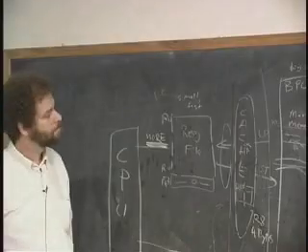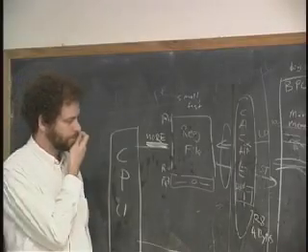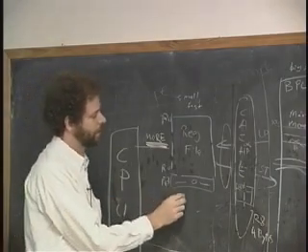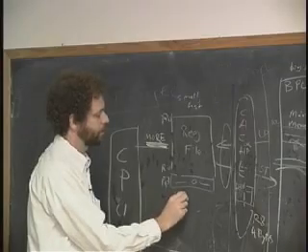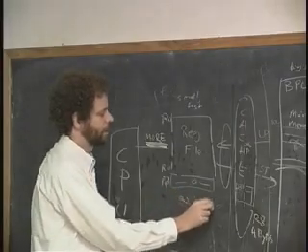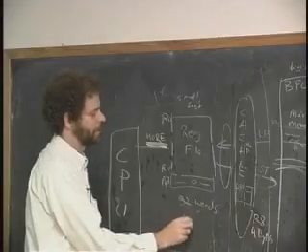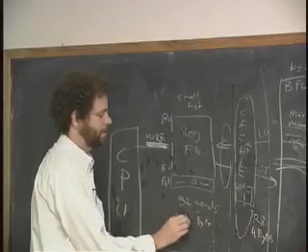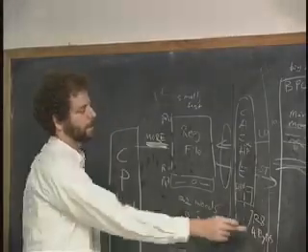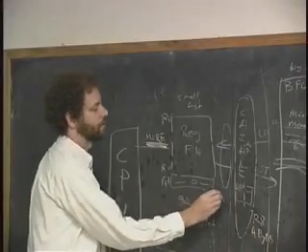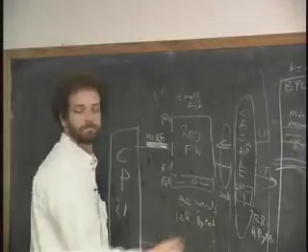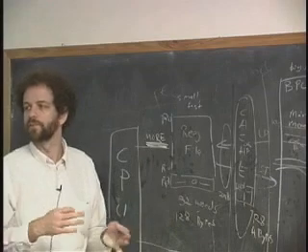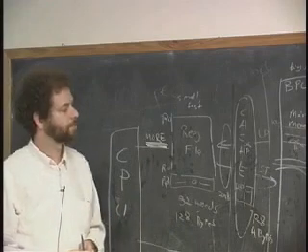Stepping from register to cache 1 to cache 2 to main memory, what's the ratio of the sizes? Well, I can give you typical numbers. This over here was on the order of 32 words, which in this case of our machine was 128 bytes. This is 128,000. Something in here may be on the order of 2K bytes, something like that. But each time kind of going up by a factor of 100, a factor of 1,000, something like that.